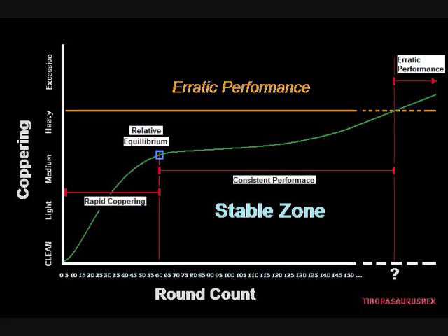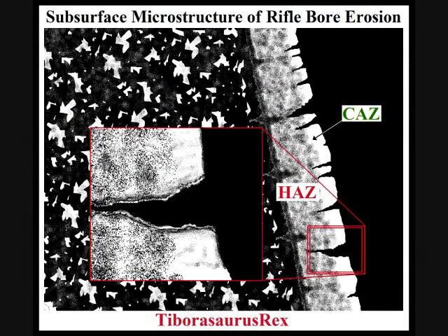But just to recap those two things, the coppering: you have microscopic pits inside the bore like we discussed earlier. You will get copper in those, and that will augment differential expansion, because copper is going to expand with heat differently than steel will. And so that'll assist with some of the microscopic thermal erosion mechanisms and mechanical erosion mechanisms, but you've got to weigh the two things against each other. Which is going to cause more problems for us in our long-range precision rifle?